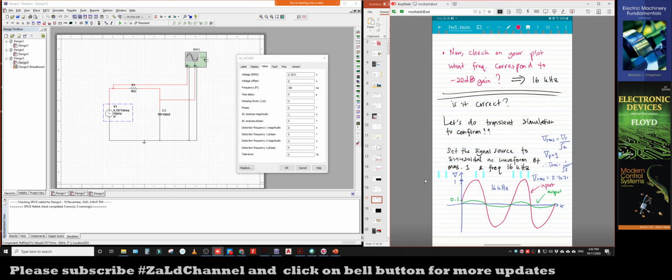We want to put the input signal as a 1 volt sinusoidal signal, and we set the frequency to 16 kilohertz, which in our AC analysis just now corresponds to negative 20 decibel, meaning the output signal is 10 times smaller than the input signal. If we put the input signal at a magnitude of 1, the output signal must be 0.1, which is 10 times smaller.